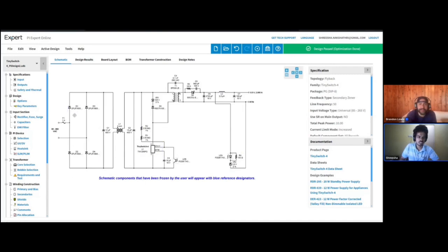So you have here four diodes which form the full bridge rectifier, and you have your capacitor, which is storing the voltage generated here. This is similar to the simplified diagram shown before. So you have your flyback. No, this is just the filter. So this would be the EMI filter, and again you have a capacitor here to store the filtered DC value. So you will have a high voltage DC value here. At least for the Indian voltage, if you have AC here, for example 230 volts, it would be something like 315 volts here.